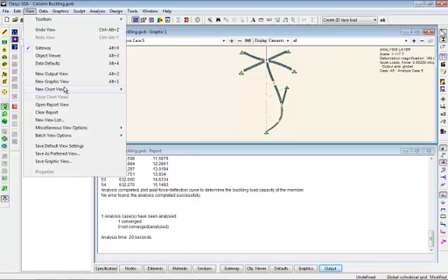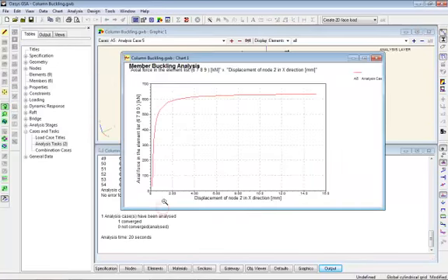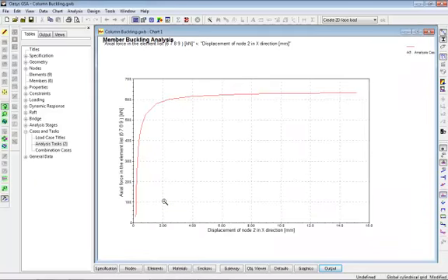If we go to our chart views, non-linear analysis, just enlarge it a bit, we'll see as the axial force increases, to begin with, the deflection at the midpoint is reasonably linear, and then it starts to go and finally fails. And this value here is actually about 630 kilonewtons, which is just 10 less than the linear elastic calculation.